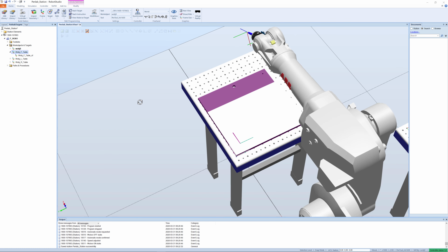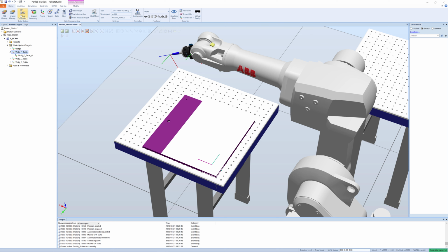And the next thing is actually to get some robot targets defined. What we're going to do is make sure that we have the right work object here. We can set that already, where work object 0 defines that everything is related to the base of the robot. That could work for the starting positions, but we work all the time relating to the front table.